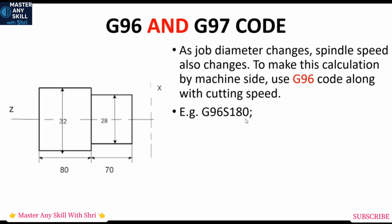How to calculate this cutting speed we are going to see, but for now just remember you have to give G96 code along with cutting speed, so that the CNC machine understands that the diameter is changing in the workpiece, and according to that CNC will do its calculation.